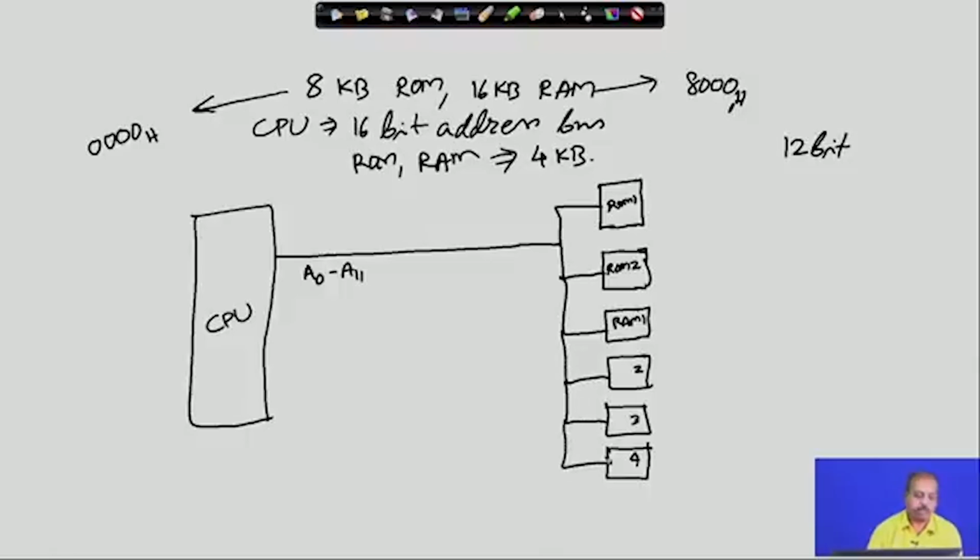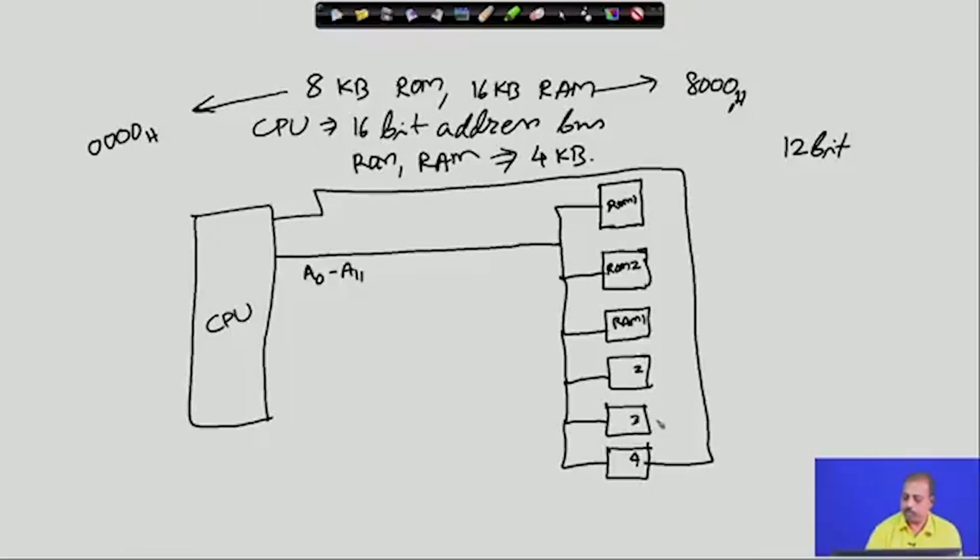This part is done, and similarly the data bus. The data bus is 8 bit and connects to all the chips. The data bus is bidirectional and the address bus is unidirectional. So, that is done here. Address bus is like this. Now, this is the basic connection.